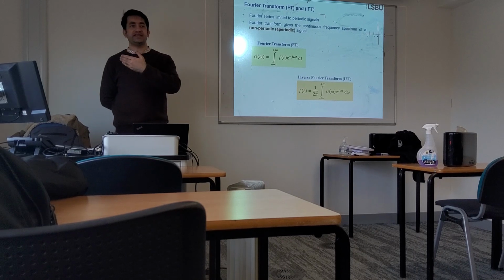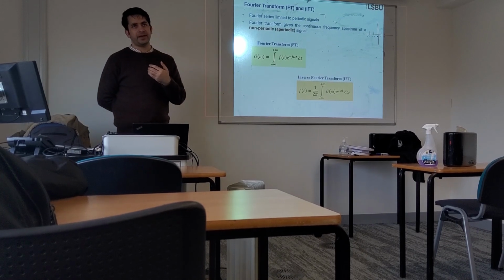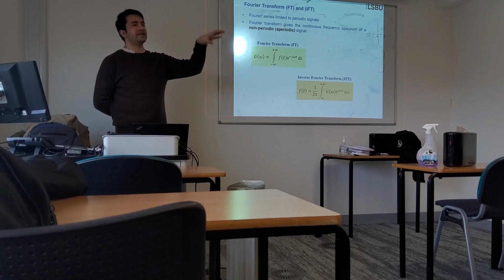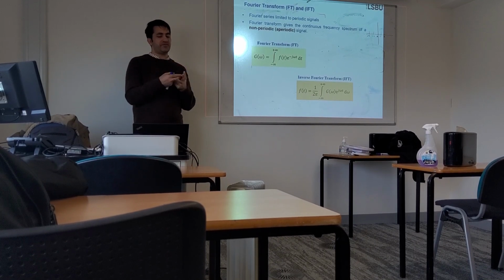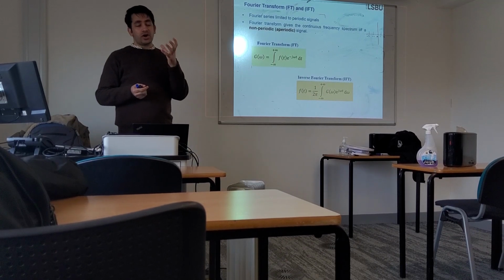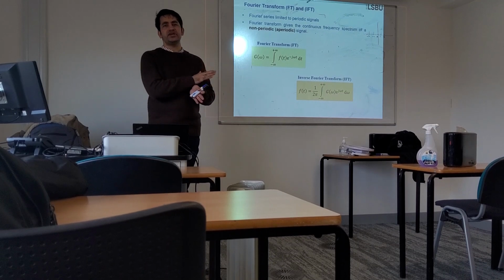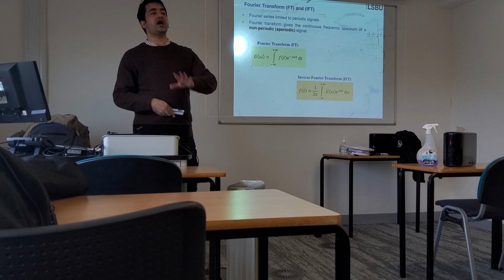We deal with AC signal that is actually coming from our socket. And most devices are designed for a single frequency, which is 50 Hertz, or in some countries 60 Hertz. But because of so many loads connected in the power system, for example motors, generators, heaters, and so many things, noise generates in the power system, and instead of only 50 Hertz, you have many other frequencies in the signal, which are called harmonics, which are undesirable.